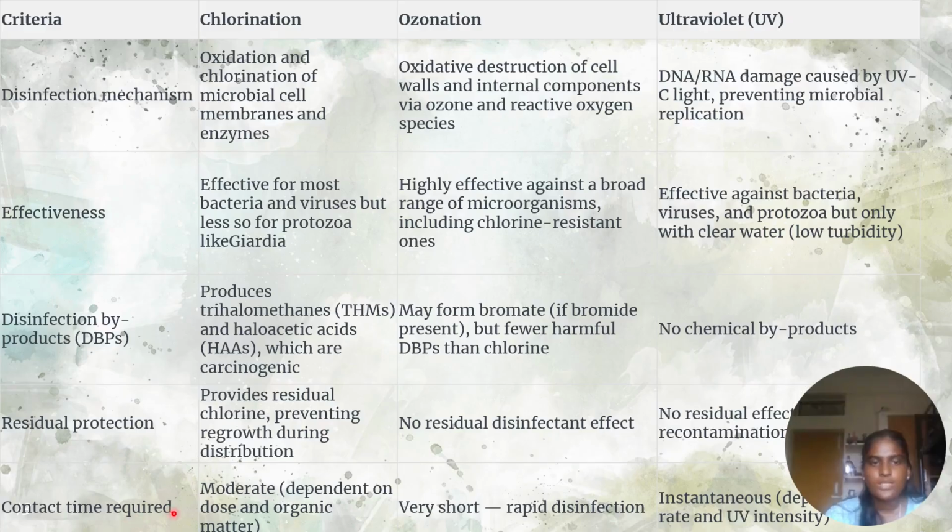Then the required time is at a moderate level for chlorination. Ozonation is very short and rapid disinfection. With UV radiation, we instantly degrade all the organisms.